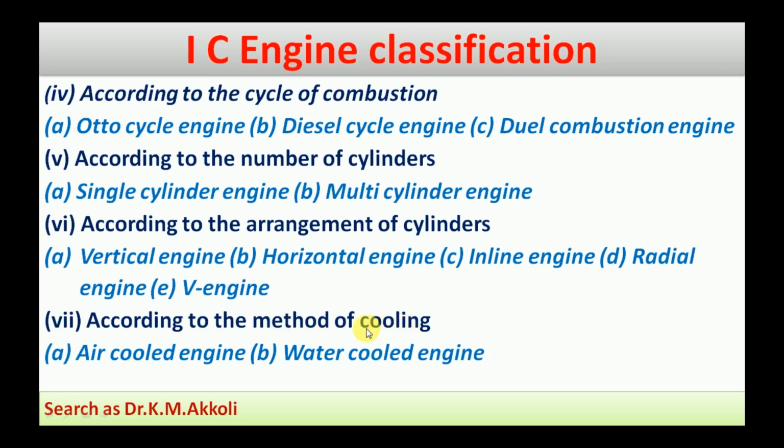During combustion, whatever heat is released is conducted through the cylinder walls and the cylinder head, and the cylinder head as well as the cylinder wall has to be cooled in order to reduce damage to the engine, and also to have better performance. That's why it should be cooled. There are two methods of cooling: the air cooled engine and the water cooled engine.